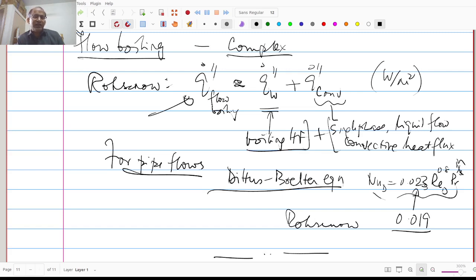And from that, we looked at the various problems that we had looked at in laminar, the forced convection over a flat plate. We looked at how the near wall flow behaves, how the core flow behaves, and then from that we were able to extract 2-layer and 3-layer models and power law models for doing integral analysis and getting predictions for wall shear stress and heat transfer coefficients in turbulent flows.